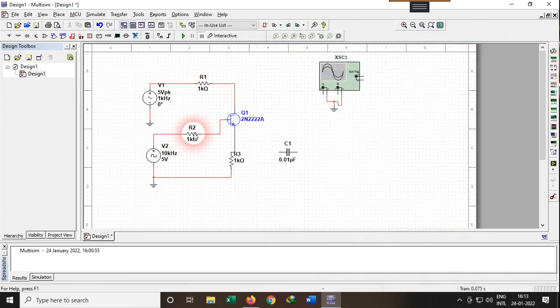I'm not going to take a new resistor. I will just copy this resistor from here and paste it here. Okay, done. So I will just rotate this and move it here. Now it looks okay. So I'm going to connect this low pass filter to this portion, so that the input for the reconstruction circuit would be taken from the output of this sampling circuit.